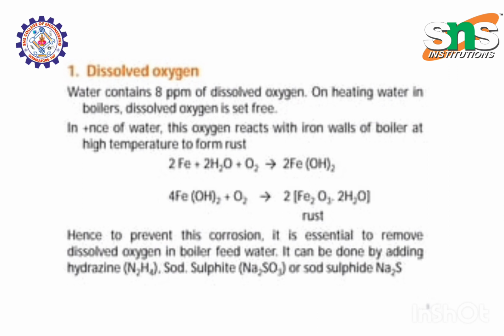The dissolved oxygen can also be removed by the mechanical deaeration method. In this method, the dissolved oxygen is removed from water when water is allowed to fall slowly on the plates fitted inside the tower. The sides of the tower are heated and a vacuum pump is also attached to it. The high temperature and low pressure maintained inside the tower reduce dissolved oxygen in the water.